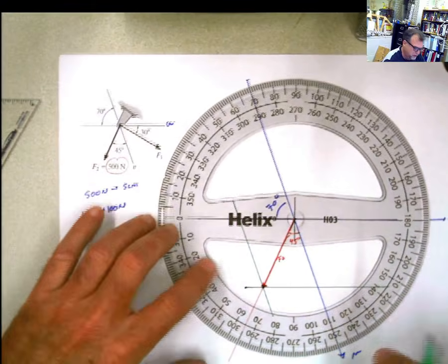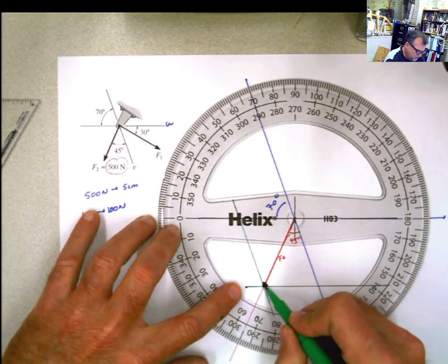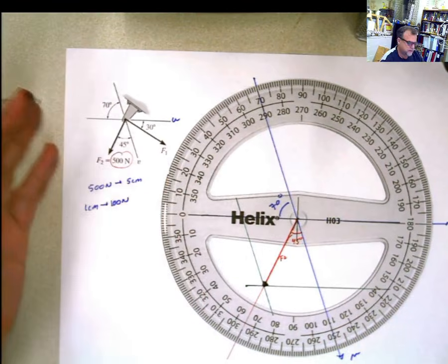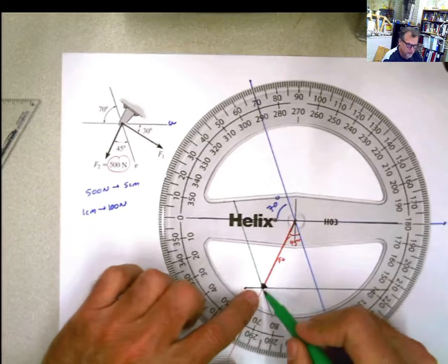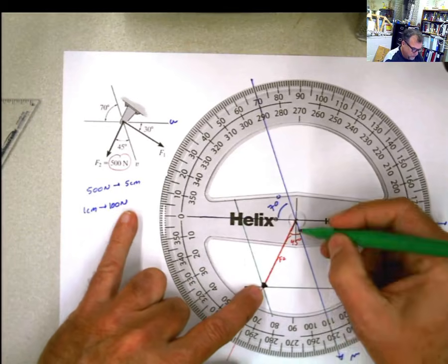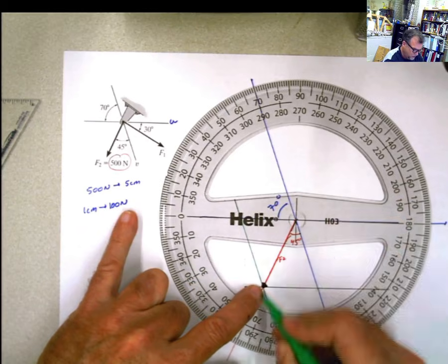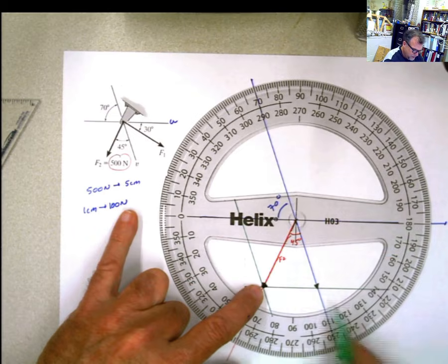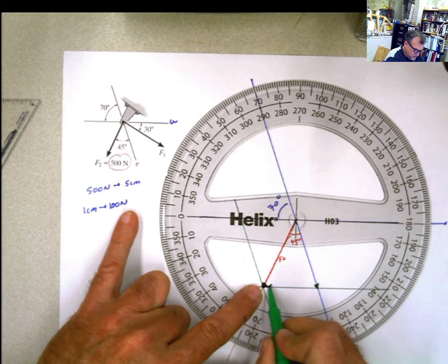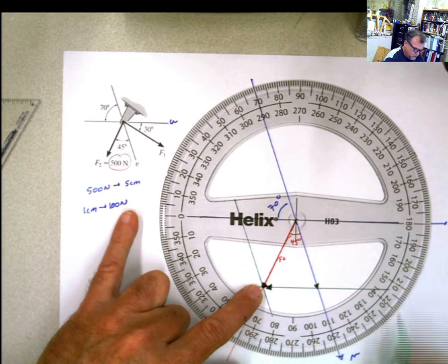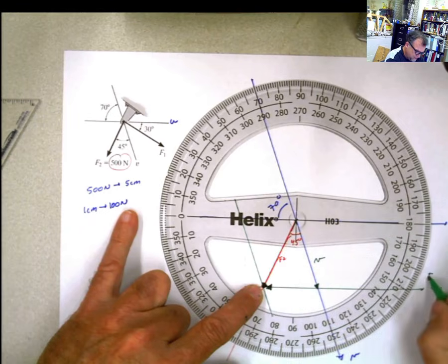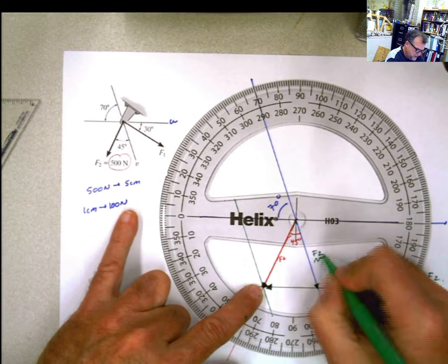How do we know the direction of the components for that force now? Well, remember, you have to go tip to tail. This is like doing addition, the same thing. So if I add the two components, I have to get the force. This is my force 2. So if I want to go from this point, which is the beginning, to that, this component has to point in this direction, and the other component has to point in that direction. What is this component? This component is going to be the u component, my F2u. This is going to be my F2v.